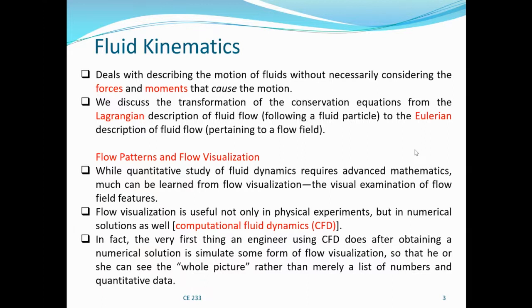In fact, the very first thing an engineer using CFD does after obtaining a numerical solution is to simulate some form of flow visualization so that he or she can see the whole picture rather than merely a list of numbers and quantitative data. So here we're still explaining the importance of flow visualization. It's very important even if you use CFD to get a numerical solution, because in computational fluid dynamics you normally